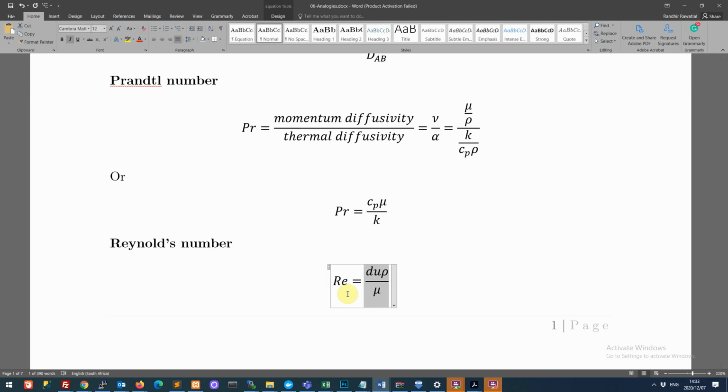It might be that we are designing a pump for that pipeline, and we are expecting that the pump is designed for turbulence, whereas we are suddenly sending laminar flow. Those kinds of issues can result in improper behavior and lead to failure of all types. So if we know that the fluid is behaving in a particular way in one pipeline, and we want that same behavior, then we try to keep the Reynolds number constant. And so you see these dimensionless groups help us to scale our systems.